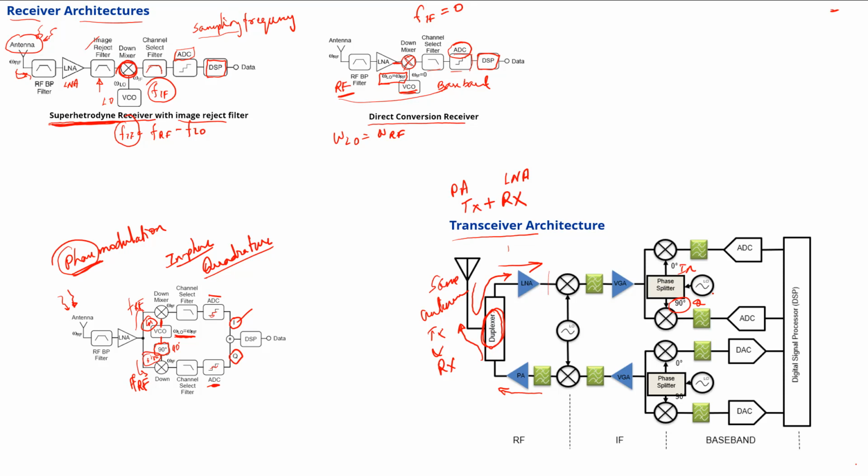And then in the transmit chain, the digital to analog converters are used, essentially translating the low frequency signal through a suitable choice of local oscillator to a high frequency, but that is done in stages. That means it's done to the intermediate frequency first, omega IF, and then the second level of mixing happens, where omega IF is converted to omega RF. So this is one kind of typical transceiver architecture that is very commonly used.